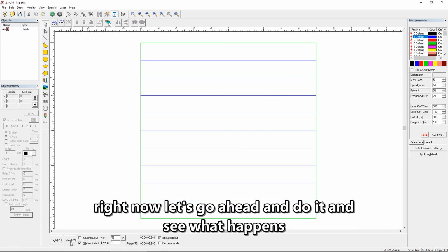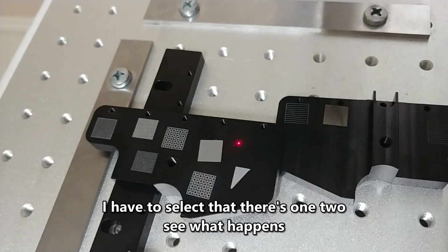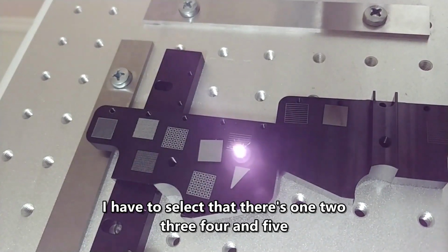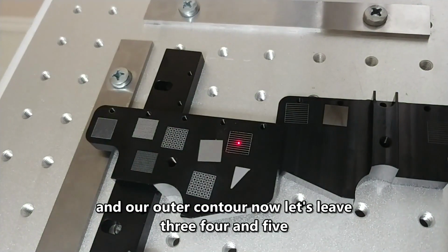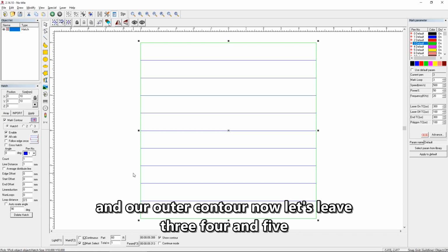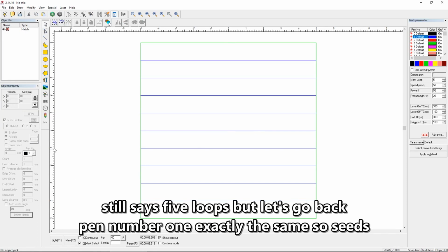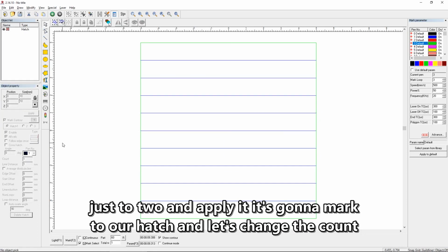Let's go ahead and do it and see what happens. I have to select that. There's 1, 2, 3, 4, and 5. And our outer contour. Now, let's leave pen number 1 exactly the same. So see, it still says 5 loops, but let's go back to our hatch and let's change the count just to 2 and apply it. It's going to mark 2 times.